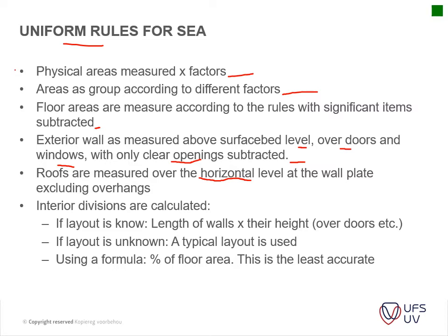Then the length of the walls and their heights is measured. So please take note of this. So this is the physical area that the wall will actually cover. So it's the vertical height of your walls. The layout: if the layout is unknown, a typical layout is used.